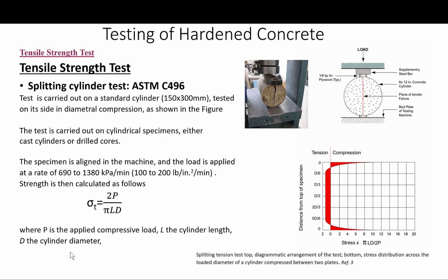As you know, it is not practical to apply a true line load along the top and bottom of the specimen, partly because the sides are not really smooth enough, and partly because this would induce extremely high compressive stresses near the points of load application. So the load is usually applied, as I mentioned, through a narrow bearing strip of relatively soft material, as you can see here.